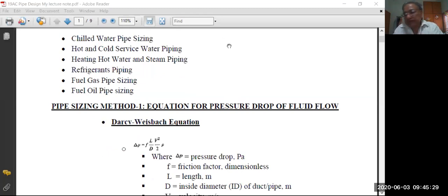design of the pipe, piping layout, and of chilled water supply and chilled water return piping layout according to the drawings. It depends where the chiller is located, where the machine room is, where the room locations are on the architectural drawing, on the site plan. The engineer should make a single line diagram of the piping layout. Once that piping layout is done, depending on the cooling load